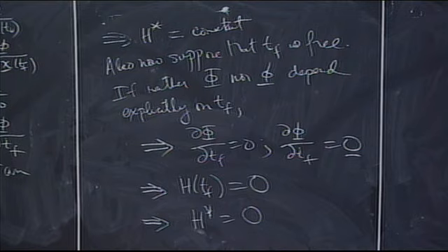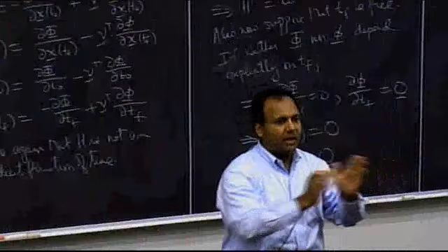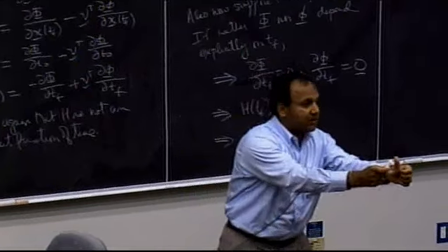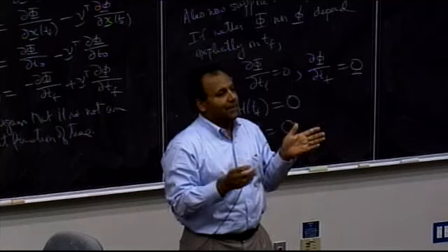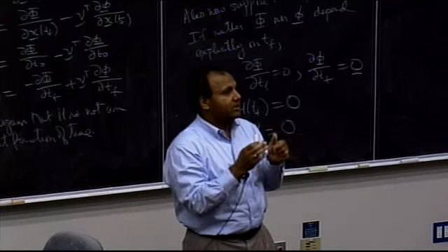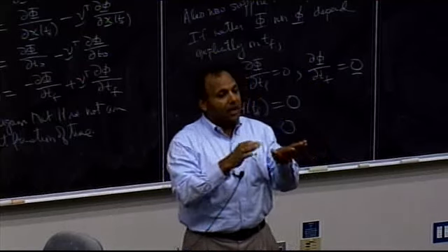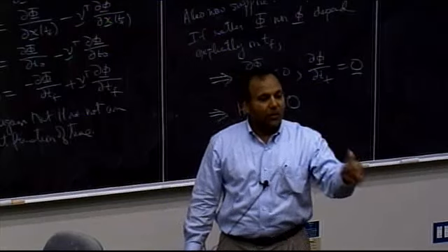In many applications, in particular when we deal with mechanical systems, like if you're dealing with robotics or vehicles, vehicles generally have what are called two-sided control. Two-sided control means that if you can do something in the positive direction, you can also do that same thing in the negative direction. Think of a car, right? Now, in reality, you can't do the same thing in the negative direction, but you can go forward and you can go in reverse, right? And in many systems, you can reverse the direction of an effect of a process.